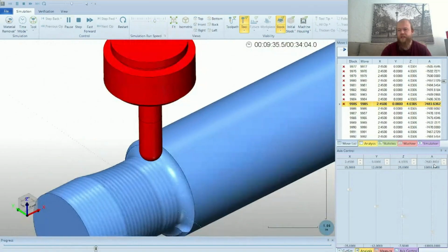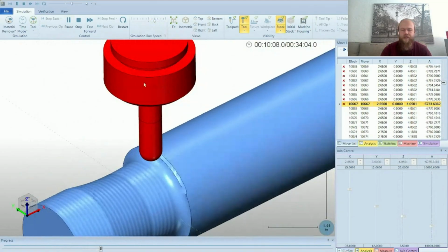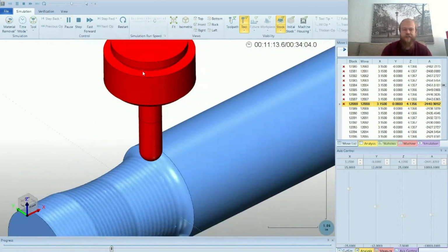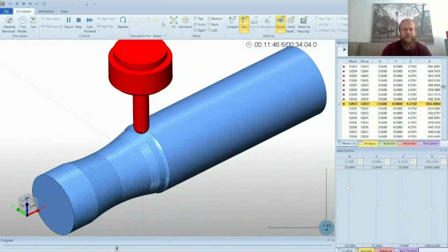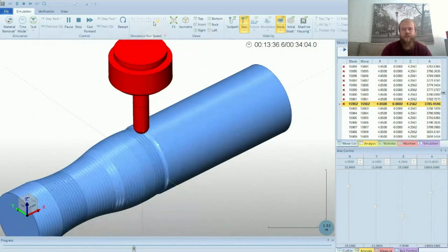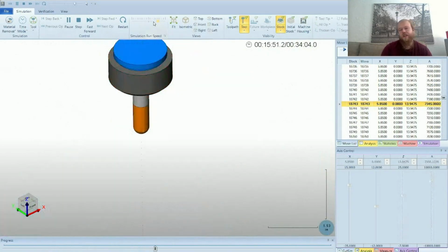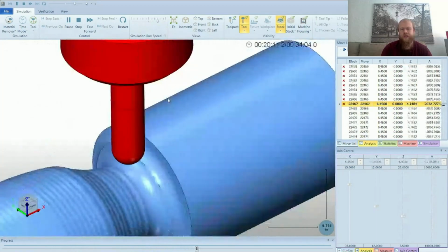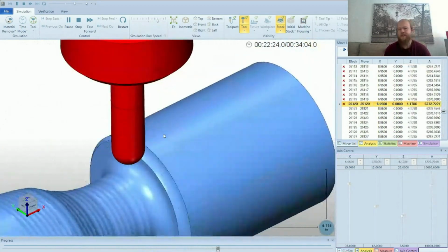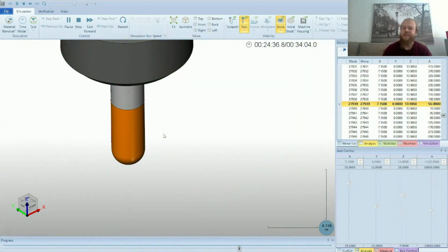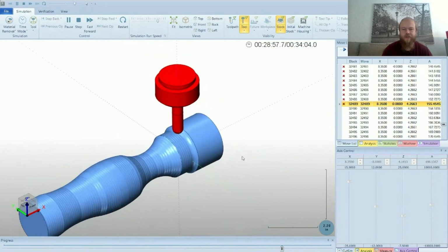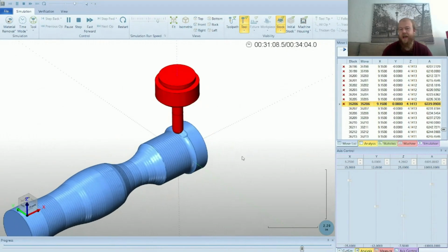And then right before it hits that limit again, it'll retract and rewind the rotary axis again if it needs to. So just to show you, this machine does that. If you don't need a limit in this regard, you can set it to infinity for the limit here in the A-axis rotation. But just to show you, we do offer that type of limit in that axis as well.